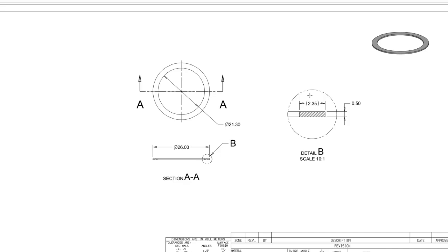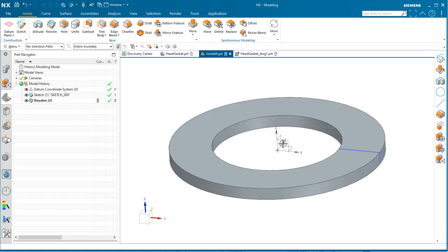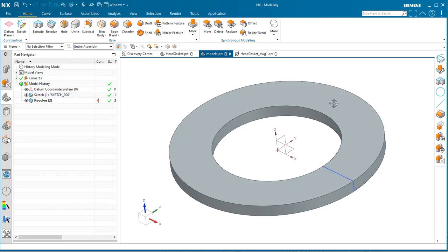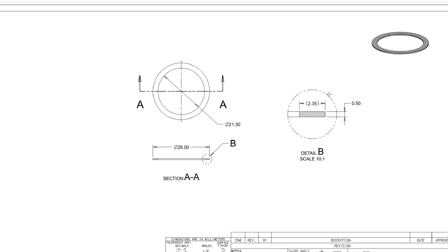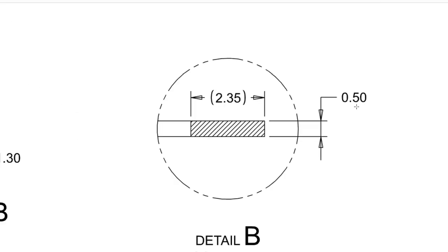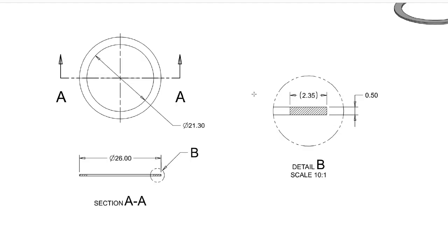One important reason that we didn't do the revolve method, where we sketch the rectangle and then revolve it around, is that if you look at the rectangular view here, we have a reference dimension on there. A reference dimension is a for-your-information dimension that is not controlling any of the geometry of the finished part. We can't reject the part on inspection of this dimension. It carries no weight, so it's a less important dimension than these other, more important driving dimensions for the diameter of the outside and the diameter of the inside. So we structured our model based on the important dimensions.